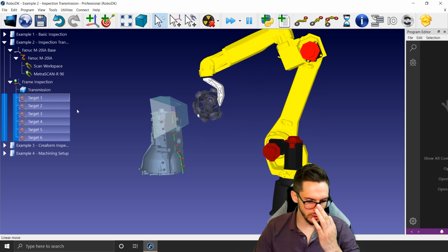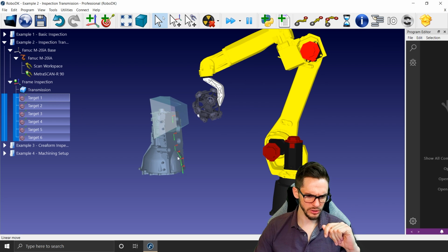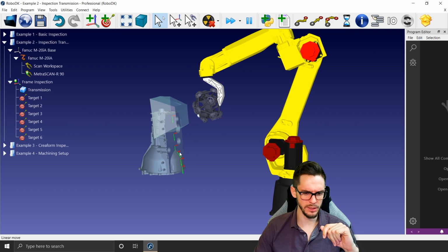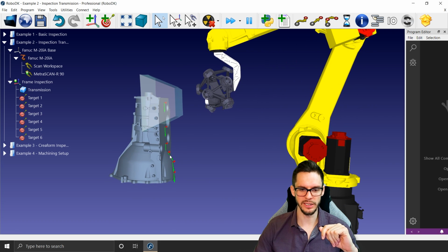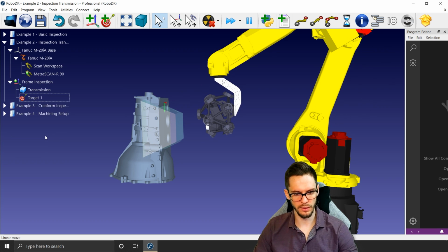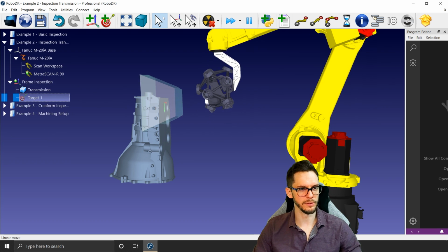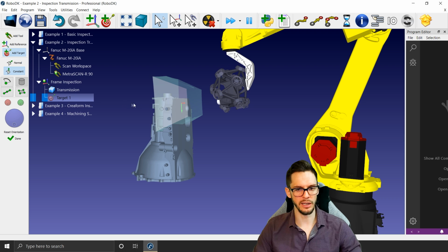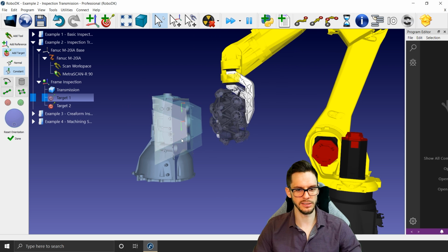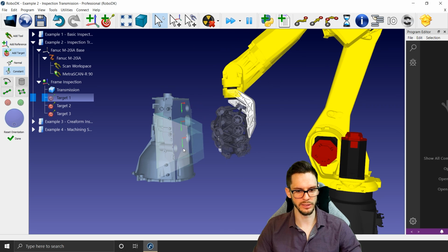But let's say that I do not want to be normal to the surface here. Let's say that I just want to keep the same distance all the time, but that I want to be in the same orientation as this one for the whole inspection. So let's delete all of them. Let's go back to the first one. I go program, teach target on surface. Here, instead of using normal, let's use constant. So now it will just stay constant to this orientation like that.